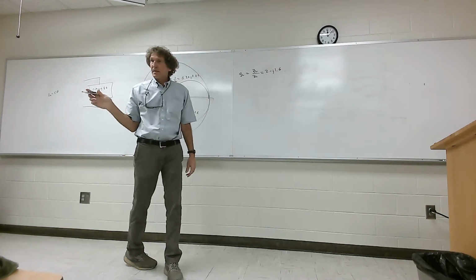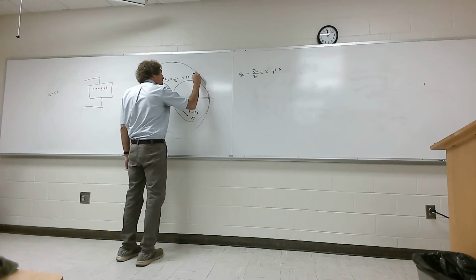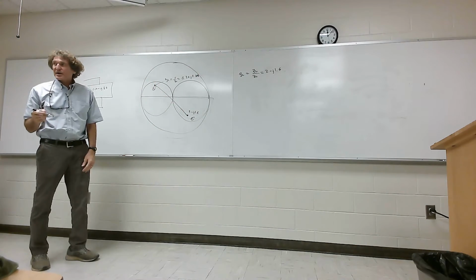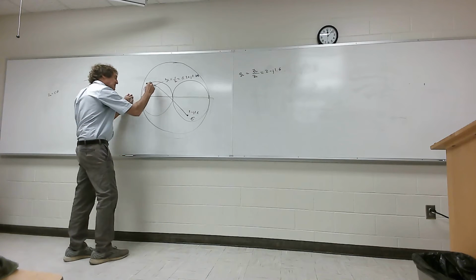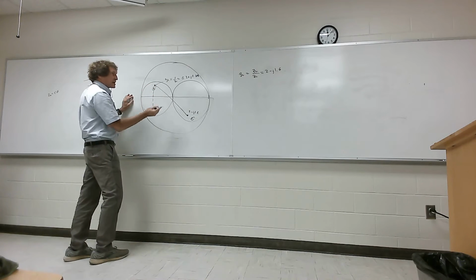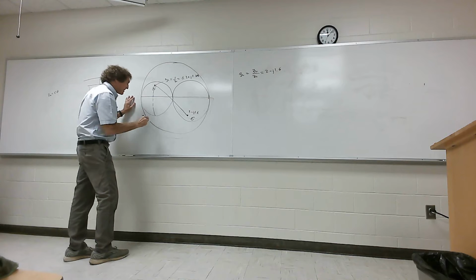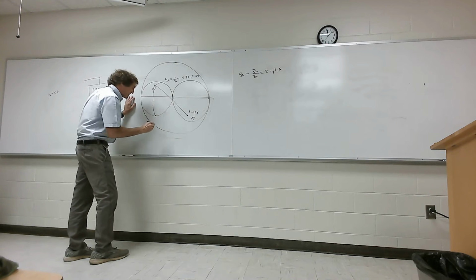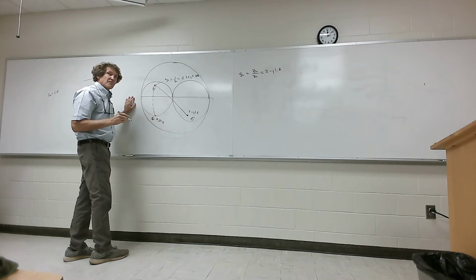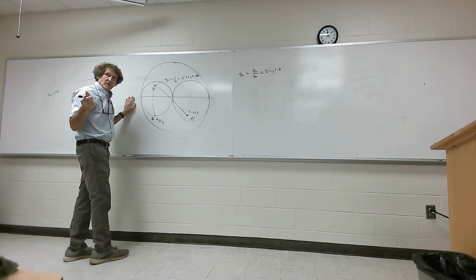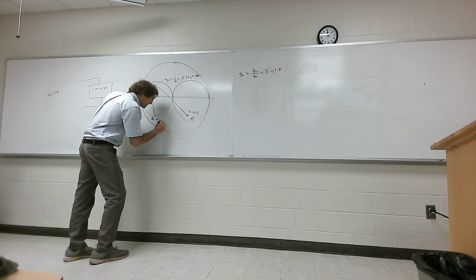Is that right? All right, now we're going the wrong way, in a sense. We're going to go not to this point, but to this point. So we come down here, we stay on the 0.3 trajectory, and we find this point here, and this would be my third point, 0.3 minus J 0.46, is that right? 0.46, correct, class?